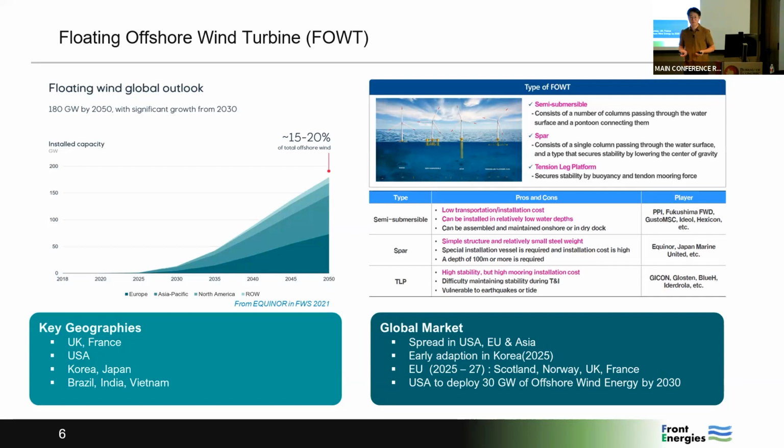For the tension leg platform, they need tendons connecting the floater and the seabed. Very tight tendons are necessary. This tension leg platform has some very high frequency resonance because of the tendons. Sometimes this resonance coincides with the tower resonance. So that's a fatigue issue. Even though they have some solutions, such as replacing the tendon material with another material, or changing the whole concept, anyway, that's the kind of thing. Anyway, these three different concepts are suggested worldwide.